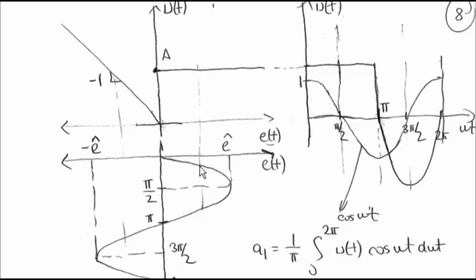It means that for a single e value, I have just a single u value. And you see that for a single e value, for this nonlinearity, I always have a single u value. So what can make this nonlinearity have multiple values at a single e value? It is a type of hysteresis type of nonlinearities, for example.